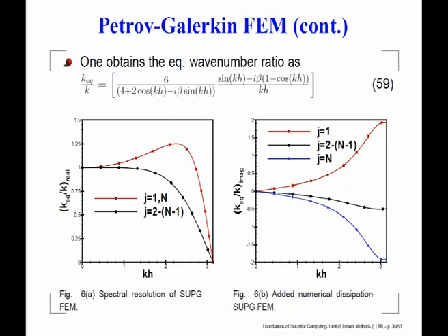You find that a significant amount of numerical dissipation is added, and please do understand this value of k equivalent by k imaginary, even at the Nyquist limit, you can see this value is something like about 0.3 or thereabout. And if you compare with what we have done in the compact scheme, this is a hugely dissipative scheme. This is a very, very dissipative scheme. Okay.